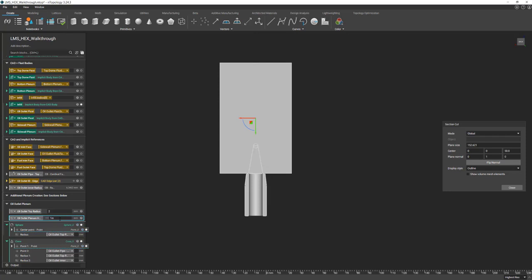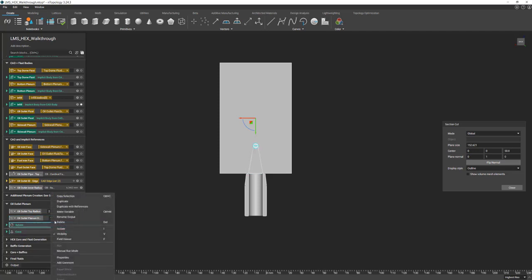So what we can do to try and figure out how large it needs to be is evaluate its exit surface area. In order to do that, we're going to union together these two segments. So we'll make these variables first, and I'm going to call this one oil outlet plenum, OO plenum, segment 1.